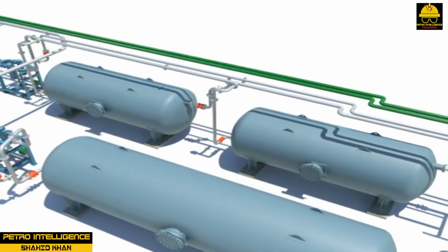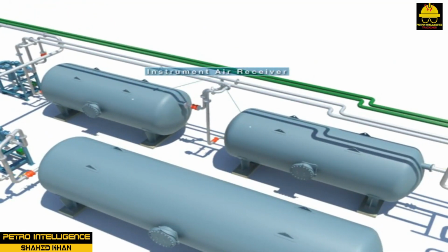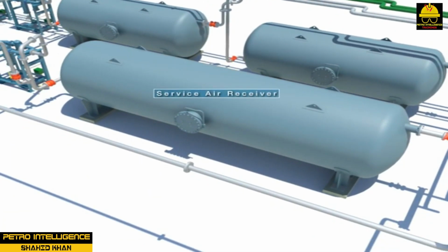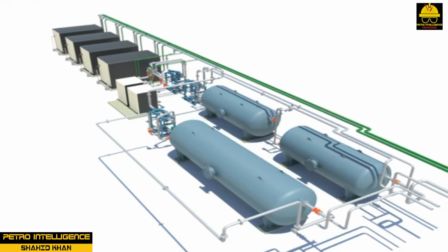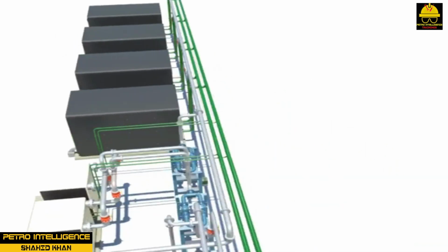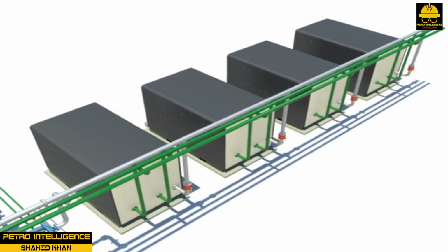At some locations, the plant instrument air system is protected against pressure failure by a tie-in to the nitrogen N2 system. Because of safety concerns, nitrogen is admitted into the instrument air system only during an emergency. An alarm or alert system is in place to warn all unit personnel whenever nitrogen is added to the instrument air header.